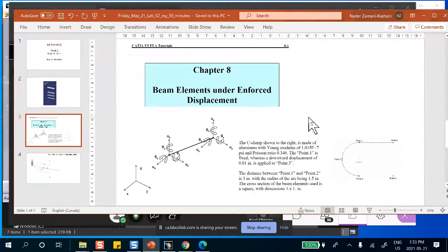There is nothing exotic about beam elements. You just draw it as basically a line or a curve or something like that. You don't draw the three-dimensionality that you showed in the case of, for example, the solid elements, or that C-clamp that we did before. But there is a caveat. These beams are very versatile elements, but they do not provide you information on stresses.